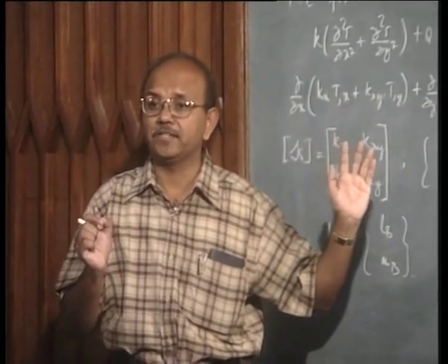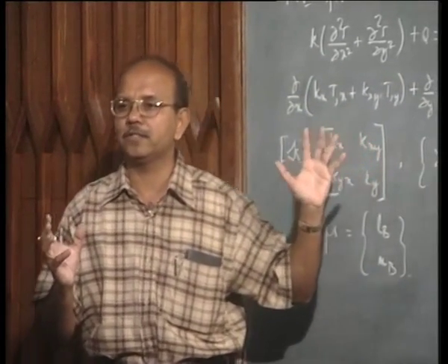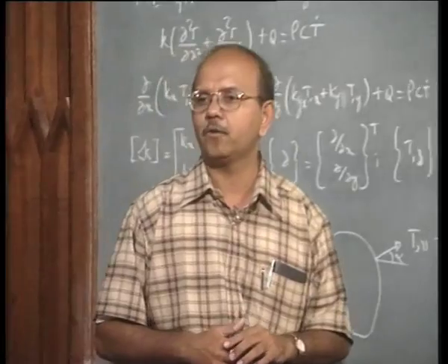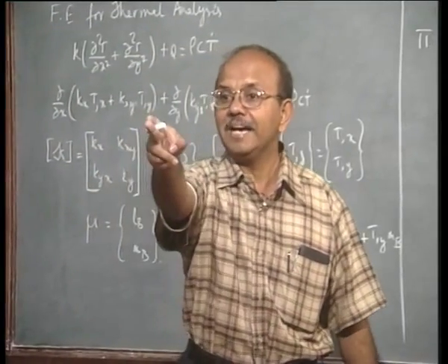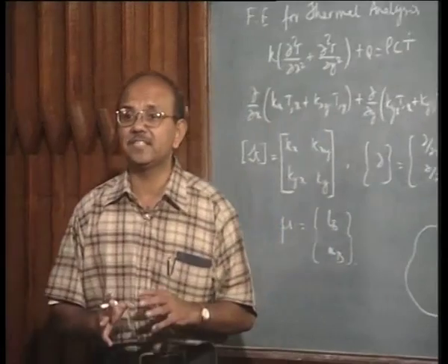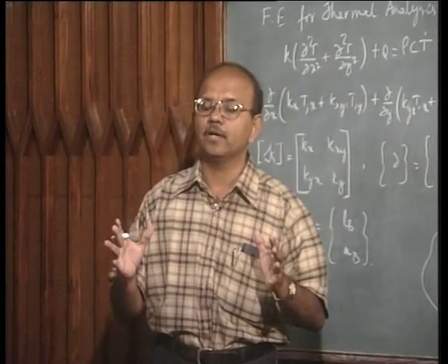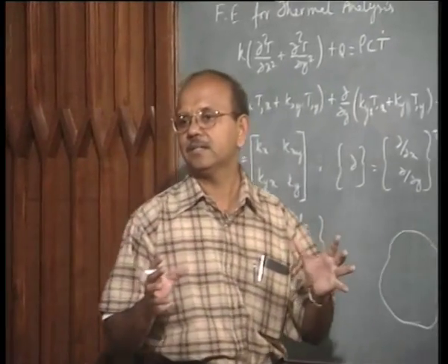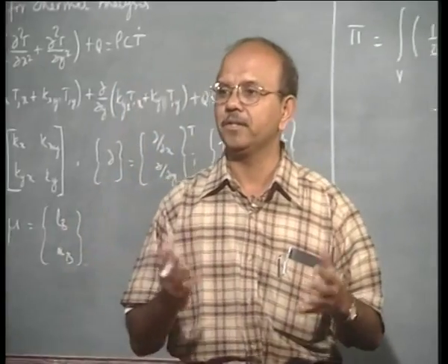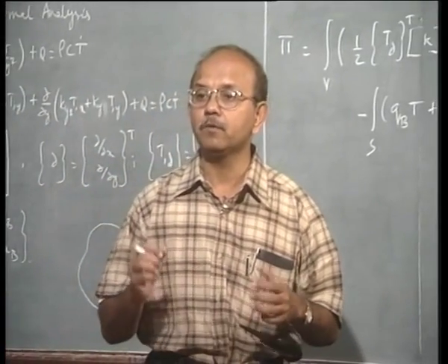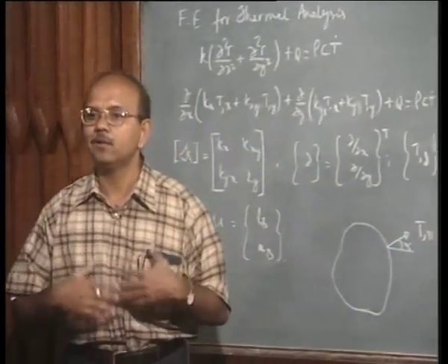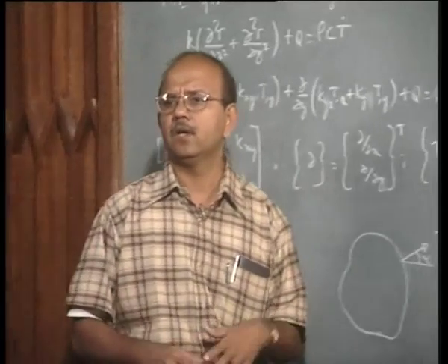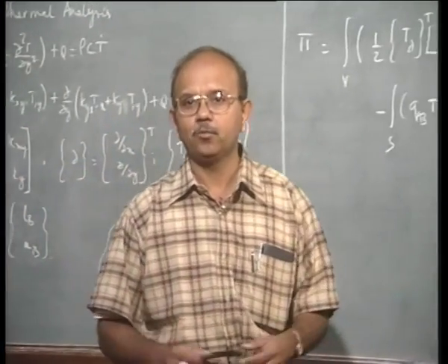We are looking at manufacturing problems. What is so very different about manufacturing, say a welding problem or a casting problem? Yes, that's it. So the temperatures are very high. It can vary quite a bit, and hence K, rho, Cp, all these things may depend upon temperature. So this will make the problem highly nonlinear. K will not be a constant. Rho, Cp, everything would change with the temperature.